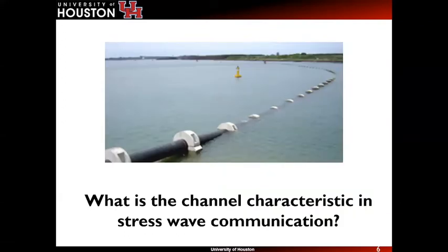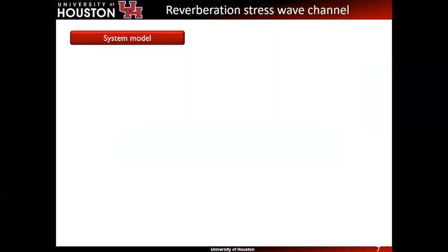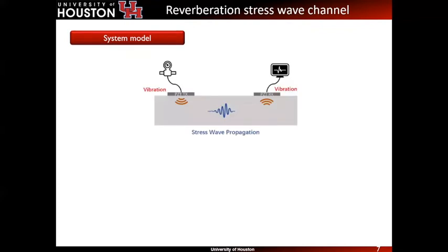In the next section, we focus on the channel characteristics. We investigate the stress wave channel from model analysis, simulation, and experiments on the testbed. Let's begin with the system model. This figure illustrates the stress wave communication system.